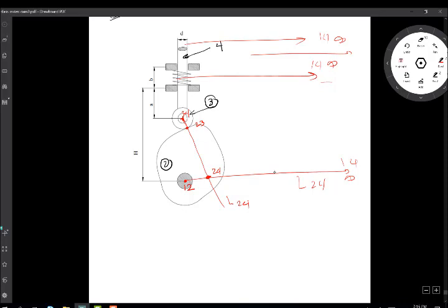It falls on the cam, link number 2, and also falls on link number 4 at the same time, because the theory says every two links share a point of common velocity, and the three points shared among three links are collinear. You can see here points 3, 4, 2, 3, and 2, 4 are collinear, among links 2, 3 and 4.